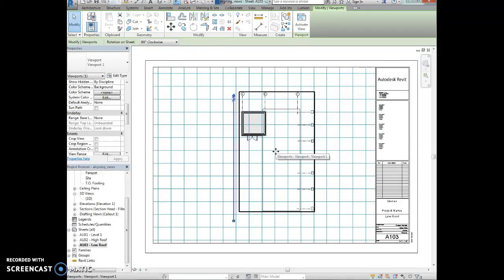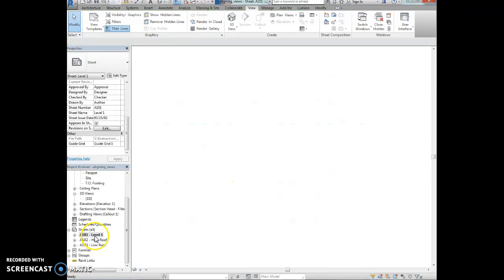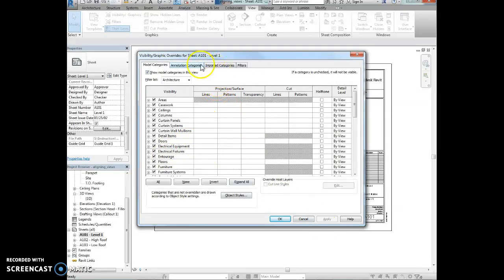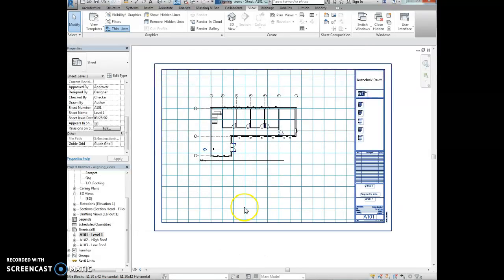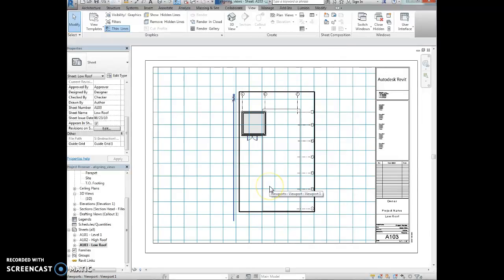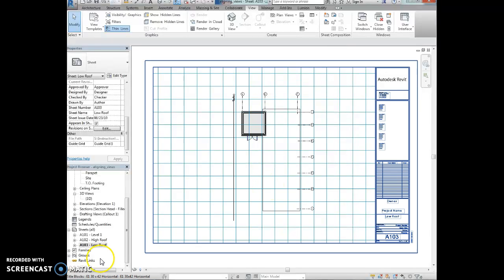So the view rotates. And the reason that I did that was just to show you that you can rotate your view, and typically in an architectural drawing, the entrance to a building is always pointing down. So a couple things that we learned. One, we learned how to align the drawings on the grid. You could type VV here as well and hide those grid lines. It didn't ask you to, but you could. So we aligned those two drawings, and then for this one we just rotated it to show you how that tool worked. And that is the end of that exercise.